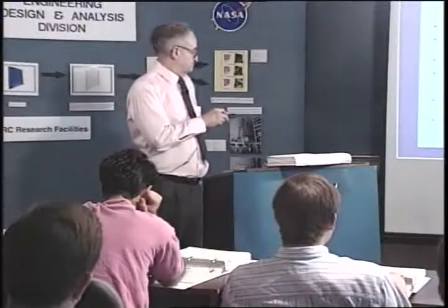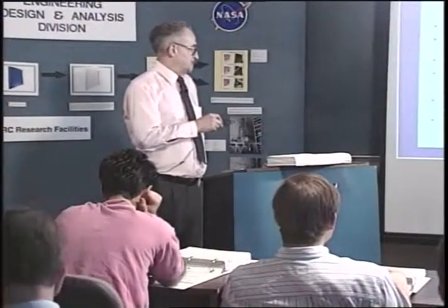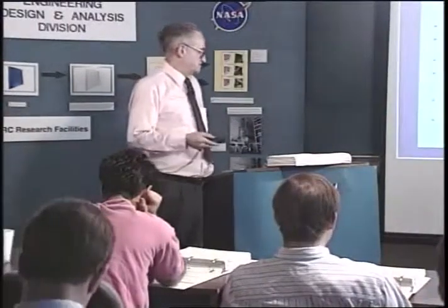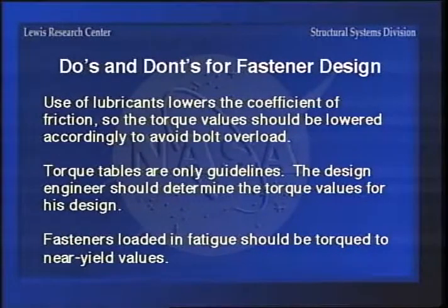And torque tables are only guidelines. The design engineer should determine the torque values for his design, because that's why you don't blindly use a torque table. It'll get you in trouble sometimes. Fasteners loaded in fatigue should be torqued to near yield values. I mentioned that earlier.